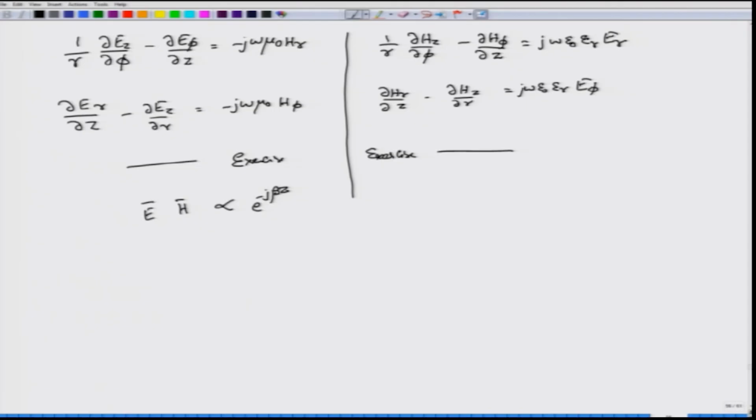That is, these are the modes that are actually propagating along the z axis, and therefore, because of their propagation along the z axis, they should have the phase factor e to the power minus j beta z. At this point, please go back to the slab waveguide in case you do not really understand why this e power minus j beta z comes up. But if you do understand, you notice the similarity between the analysis of the slab waveguide on one hand and optical fibers on the other hand. The difference is in the geometry and much more complicated expressions for the characteristic equation, as you will soon see either in this module or in the next module.